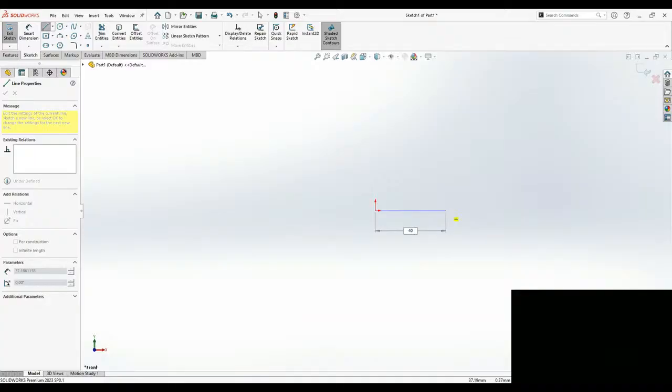If I do that, you could see just beside your cursor, you have the vertical geometrical constraint is active. If I just move it, it won't show, right? Sorry, horizontal is active. Now if I just move it like this, it is vertical. Now if I keep it like this, it will automatically take the horizontal. Now if I enter the value, if I hit enter, it takes the value, and that particular length is fully constrained. Now you could see in the status bar it shows fully defined.